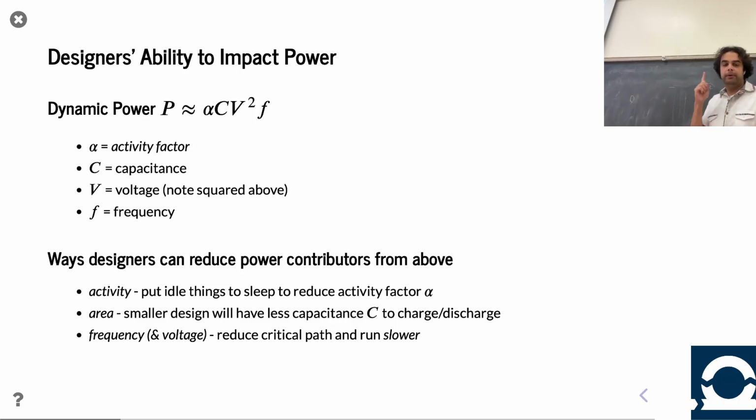Like I said, so what can you do? Activity: put things to sleep, make the design smaller, more efficient. Obviously, take less energy. Great. And of course, being very deliberate about your critical paths and your frequency and voltage helps you adjust those other parts too. Cool. Questions?